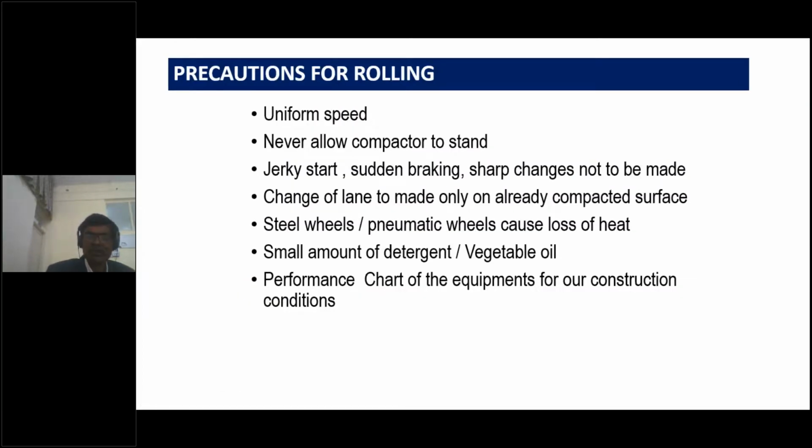So, uniform speed during the rolling. We should not allow the roller to stand on the surface: no jerky start, no sudden braking, no sudden maneuvering. We should not use water for wetting the roller wheel surface. We should use detergent or a vegetable oil.